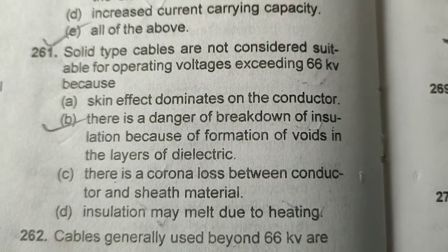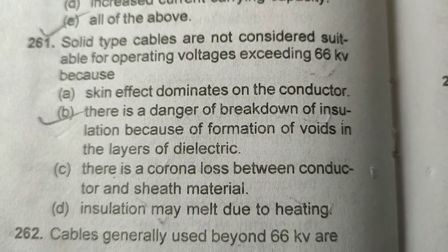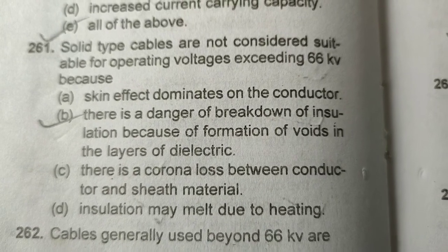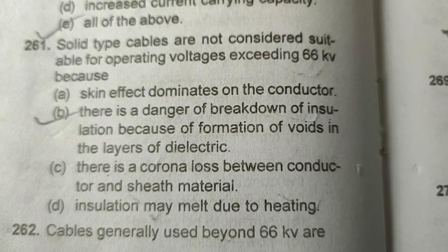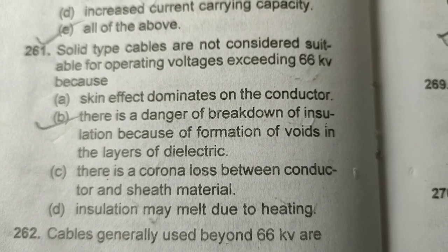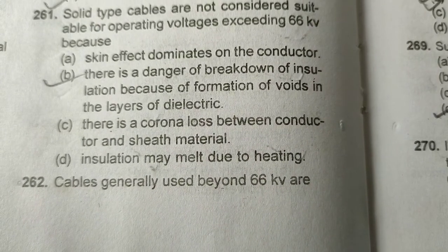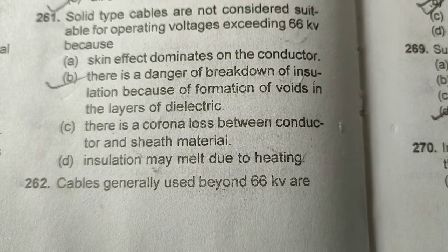Solid type cables are not considered suitable for operating voltage exceeding 66 kV because there is a danger of breakdown of insulation because of formation of voids in the layer of dielectric. Cable generally used beyond 66 kV: